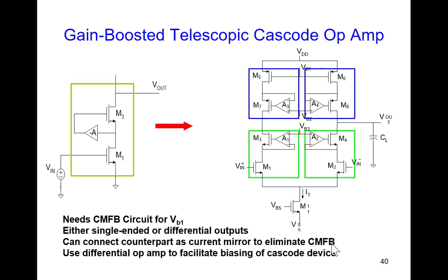And biasing is going to be a real challenge here, because this DC gain has maybe gone up another factor of 40 dBs. Anytime you have a really high gain circuit, and now we're looking at a circuit with maybe 120 dBs type of gain, this is a really high gain amplifier. If you have even a slight DC offset at the input, and you multiply it by 1,000,000, it'll saturate the output. Make sense? So biasing is non-trivial here, or is important, because we've got such a high gain on this structure.